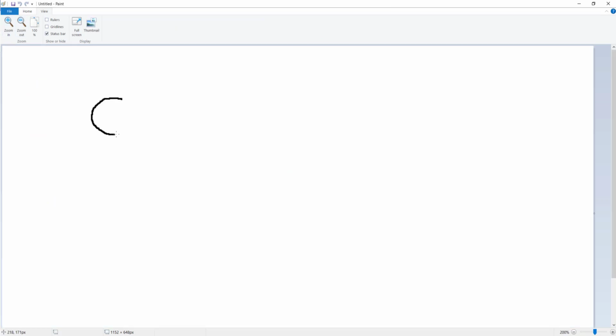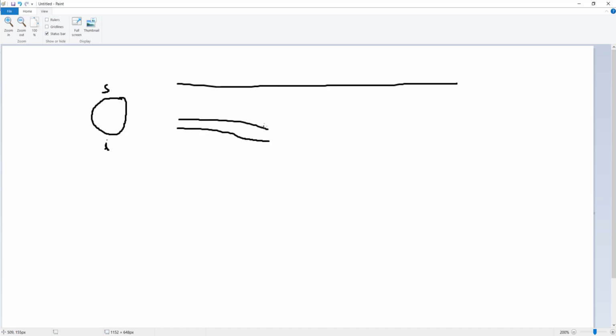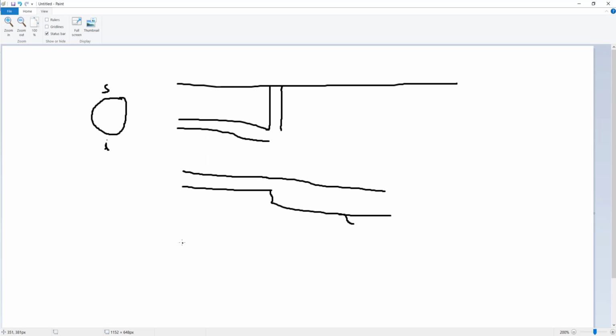So we're talking about, do we want to lay the pipe soffit to soffit up here or invert to invert? So do we want to get the bottoms the same or the tops the same? So what's happening is you've got a ground level like this, you've got a pipe coming down like this, and again, apologies for the terrible drawing, those should be straight. You come to a manhole here where the pipe is going to increase in size. And the question is, is it going to increase in size and keep the soffits level? So in other words, drop the inverts. Oops, again, terrible drawing.